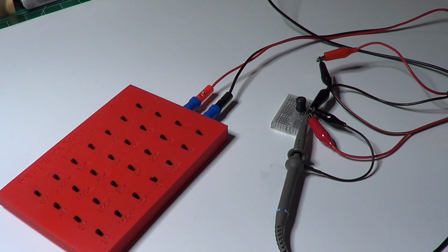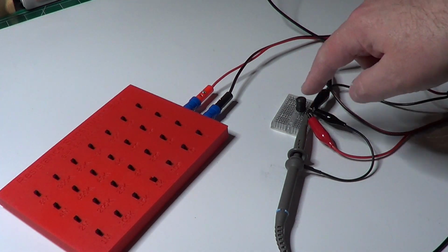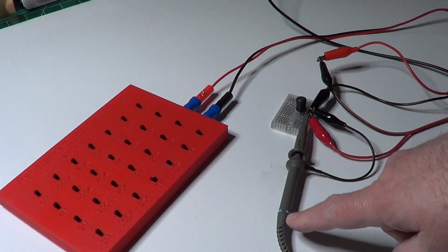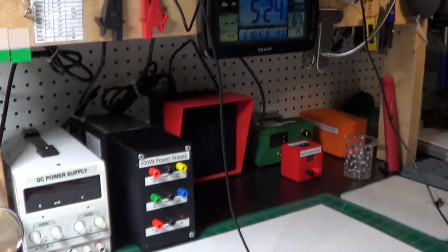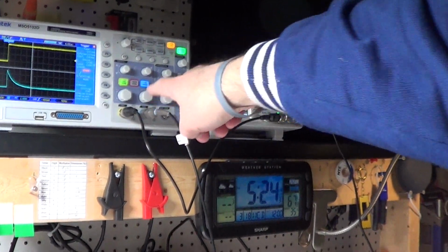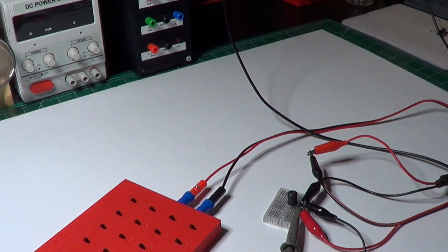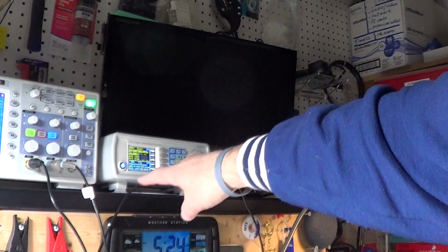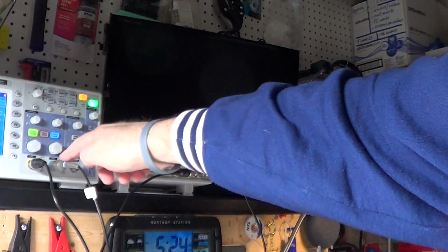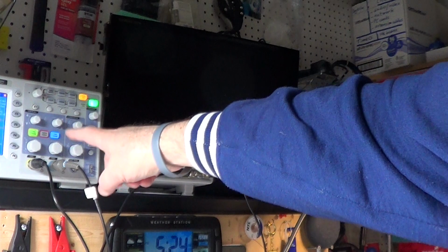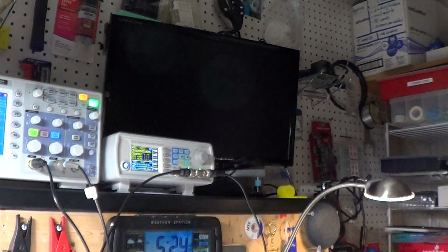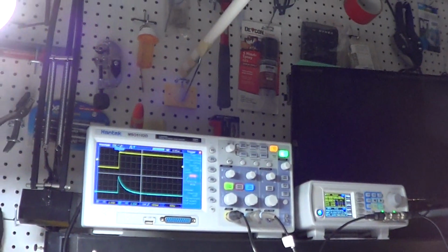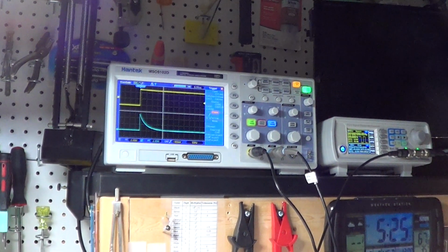And here is the circuit. The inductor is the black cylinder on the little breadboard, the resistor is made out of the resistor box, channel 2 of the oscilloscope, which is the blue one, goes up there on the oscilloscope, and channel 1 is connected directly from the generator to the oscilloscope, so we can watch both input voltage and voltage at the inductor at the same time, where the voltage at the inductor, as we said, is the back EMF. So let's take a look at what happens here at the oscilloscope. Let me zoom in so you can see better.